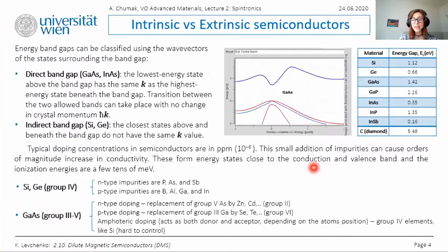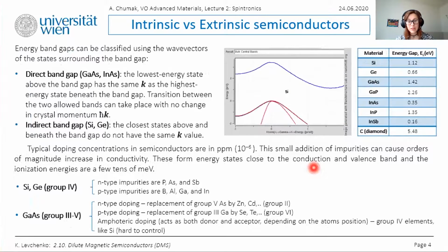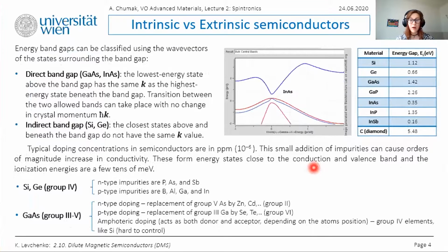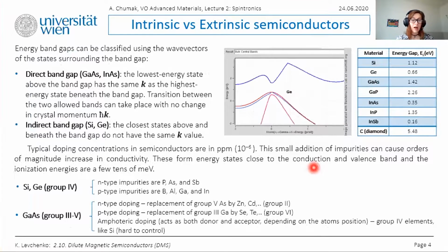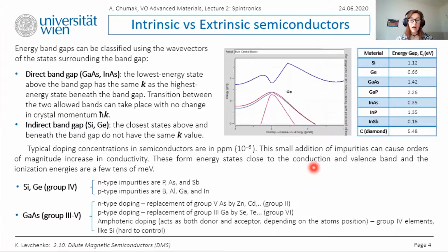Semiconductors used for fabricating devices are usually single crystals. This is because polycrystalline materials have defects due to the presence of grain boundaries. These states are located in the band gap and they can modify the conductivity. So we should always keep in mind that there are defects like shallow states that also modify the band gap. They are lying close to the band edges and act as sources of electrons and holes. Or there could be deep states, deep defects that are located in the center of the band gap. These deep states can act as traps for charge carriers and further reduce the conductivity.